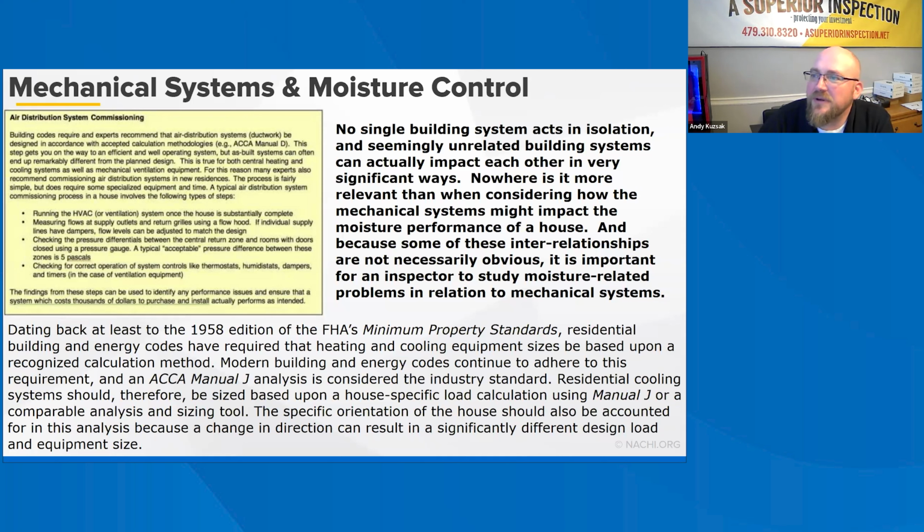This air leakage can transfer a large amount of moisture into building assemblies and can cause condensation and related problems. For example, a house with leaky supply ducts in the attic can become depressurized, resulting in warm, damp outdoor air being drawn into the building envelope during the cooling season, a particularly troublesome problem in hot, humid climates.